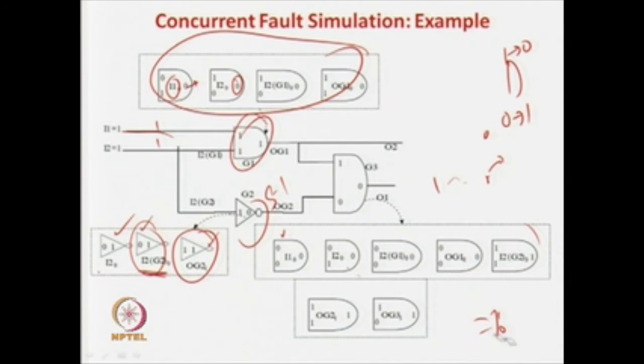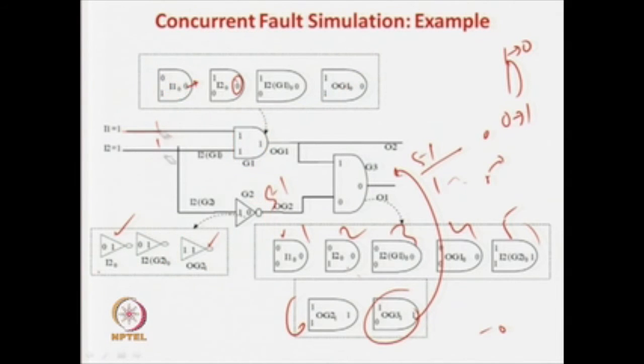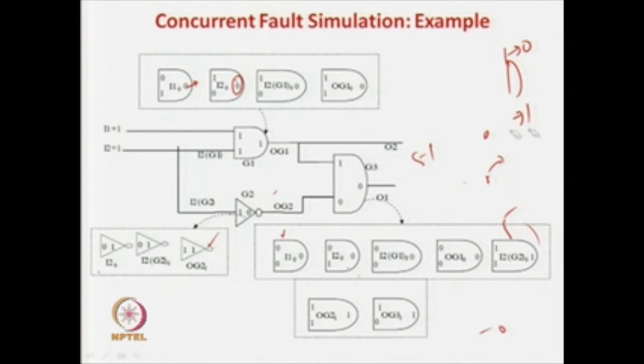So, this 5 fault, this gets 1 2 3 4 5 6, these 6 are propagated from the previous values, and this one corresponds to a stuck at 1 fault over here. So, in this case, this is how we get this fault list concurrently, we generate this one. Now you might see that the concurrent fault simulation is nothing but a deductive fault